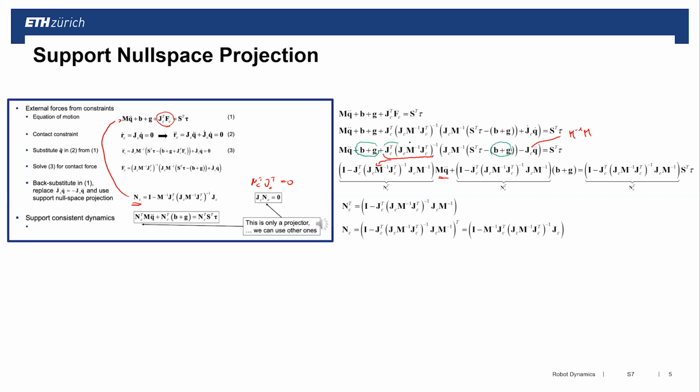So it's again this component here which goes directly in here. And the same also on the right-hand side for the torque. And what you're ending up with is this Nc transposed multiplication of the complete dynamics equations of motion. And if you have Nc transposed, then Nc is obviously just the transpose of it.